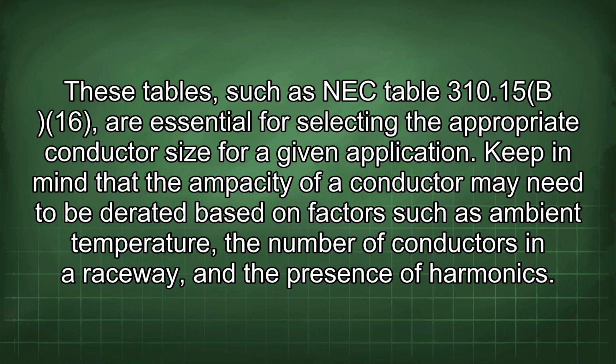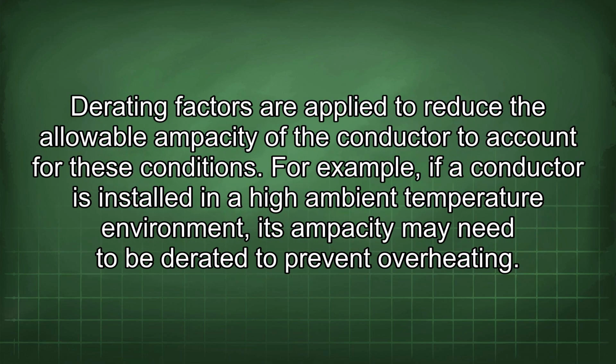Keep in mind that the ampacity of a conductor may need to be derated based on factors such as ambient temperature, the number of conductors in a raceway, and the presence of harmonics. Derating factors are applied to reduce the allowable ampacity of the conductor to account for these conditions.